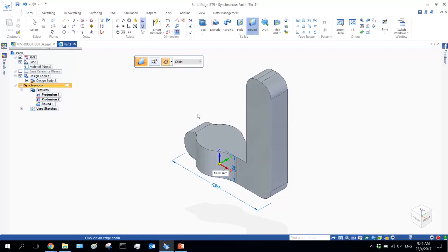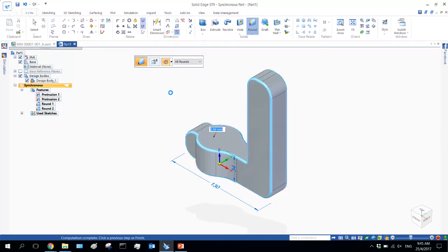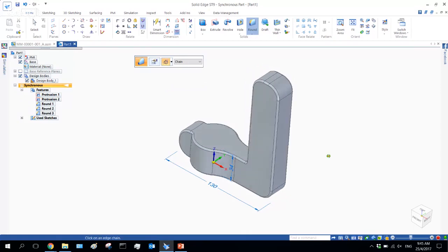And how if I want to select all the rounds over there? It's okay, just select all the fillets, insert the value, and also all the rounds. So you don't need to pick one by one. It will save your time a lot actually. And sometimes people will make an error, which is selecting a line that doesn't need to be rounded. So if you just click all the round, you can select all the rounds without error. And same thing over here.